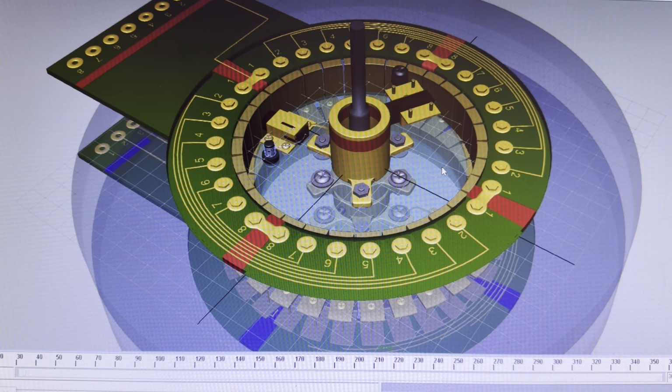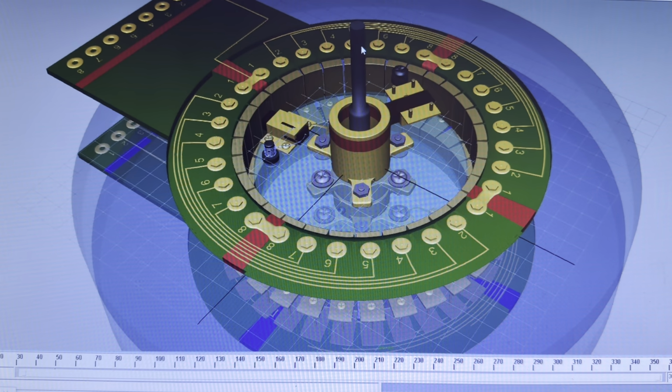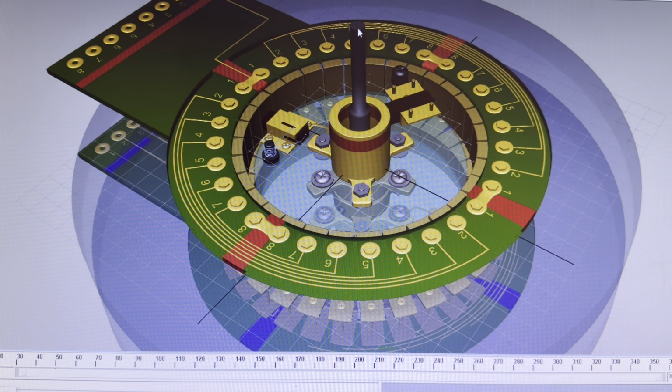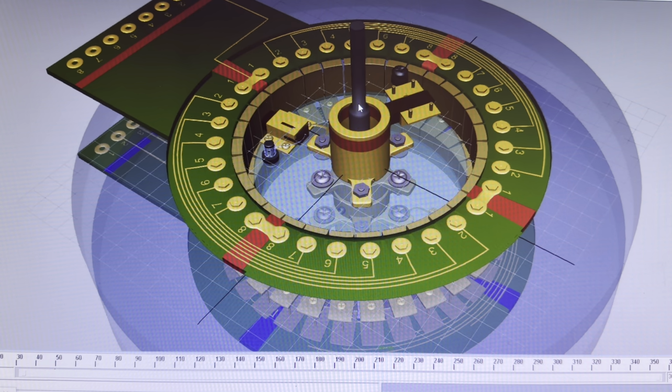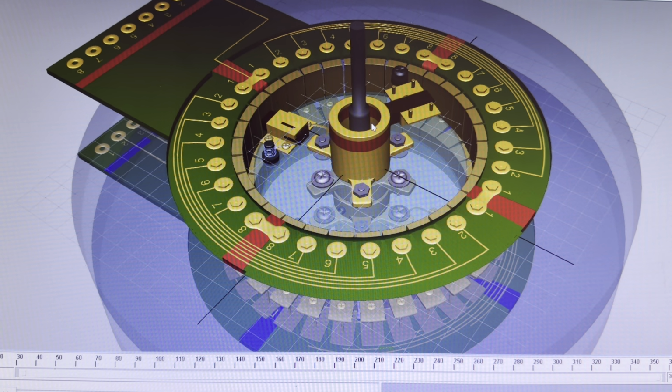And the way this convention works is based on the, follow my cursor here, from the power takeoff shaft end. So in this case, this is the part of the shaft that is elongated, and that's where we connect our future prime mover, which is the little motor that we're going to connect here. So we always face it like that. We don't go on the bottom, because the bottom doesn't have any shaft. We don't put any force, we don't take off any force, we don't input force.